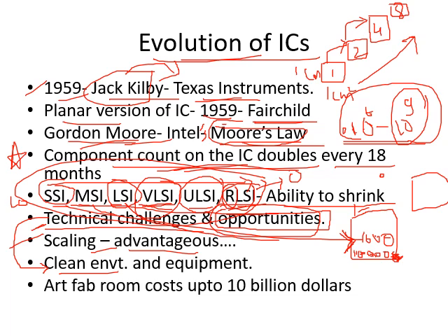So clean environment and clean equipment. All the automated machines should be very clean. This is one of the biggest challenges. Why? Because if any small dust comes in between the fabrication, then that batch will go wrong and will have a maximum number of damaged ICs.